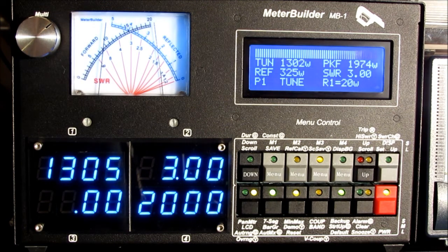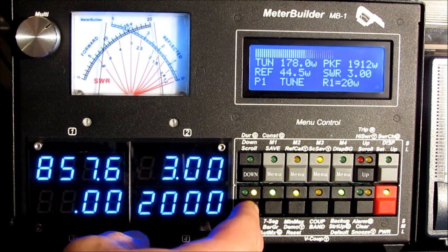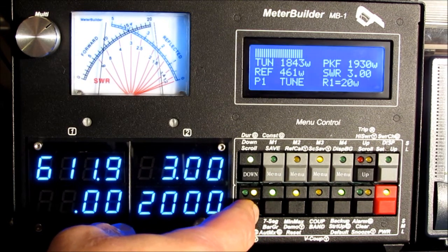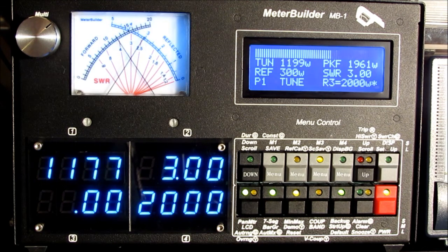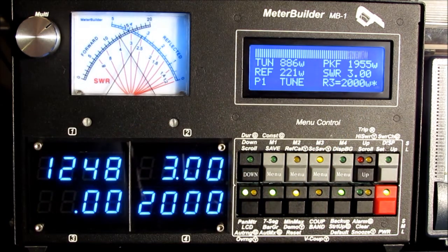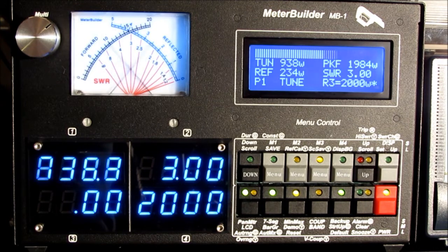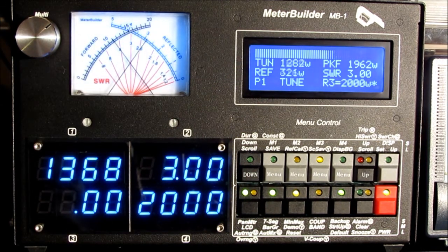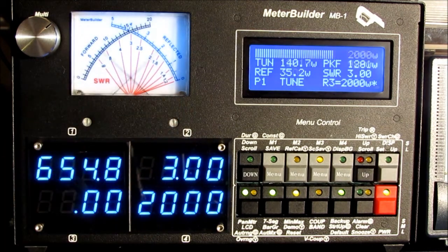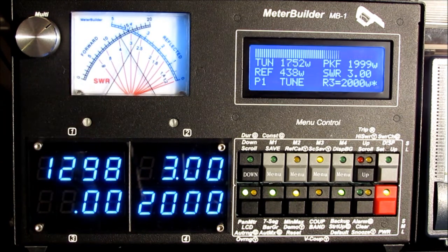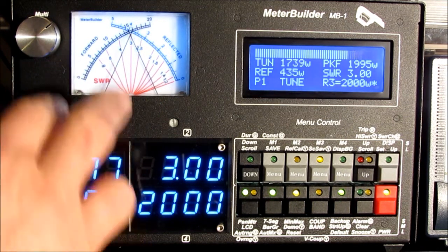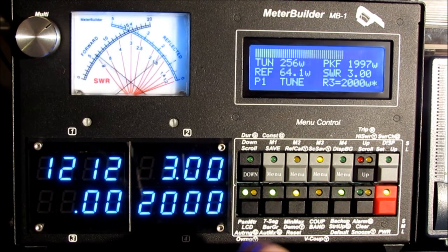So in any case, let me go ahead and put the auto full scale back on. Okay, and again, now the range is being controlled by the software to make sure that there's no overrange. So we've basically covered the third field in the panel meter menu. Let's see what we can display on the panel meter. Tune, again, is MB-1's nomenclature for instantaneous forward power. In the case of a cross needle meter, the forward and reflected power is being displayed simultaneously. And the intersection of the two needles, of course, indicates the SWR.